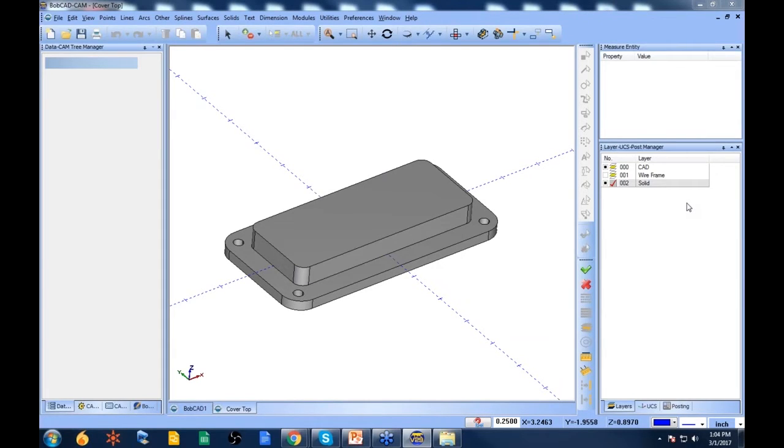We're talking about the stock wizard. When working with part files, wireframes, surfaces, or solids, one of the steps I take is to align the part with the top view. This is a standard thing that I do when I'm importing geometry or drawing a part or preparing it to be machined. Now, it's not a necessary step, but it's one I take.